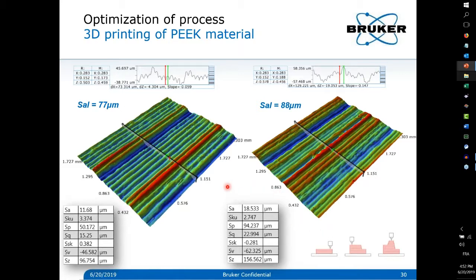So you really need to fine-tune the process in terms of printing speed and temperature of the nozzle, such that you have nice sticking between the layers. Otherwise, you create cracks and your part falls into pieces. So in that case, you are interested in having a nice, well-joined connection between every layer. This is what we call here a good process.